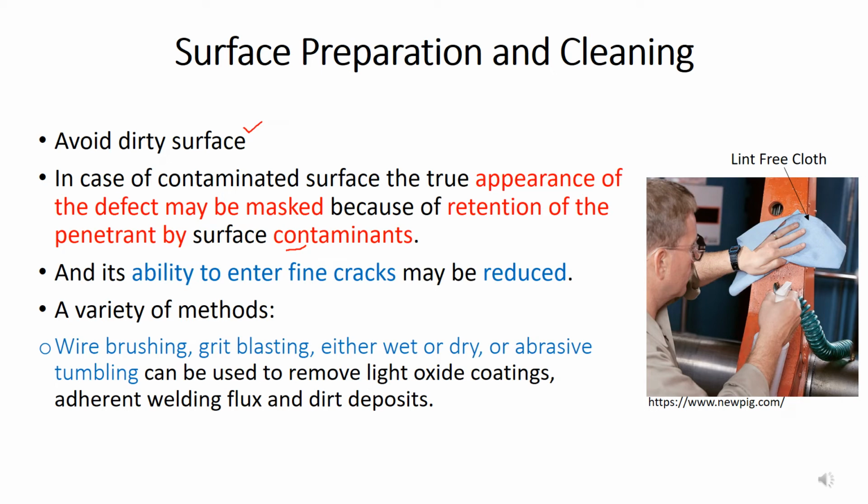Its ability to enter the fine cracks will be reduced because it is already having contaminant with it. And you can see we use a lint free cloth. A lint free cloth is a cloth which does not give any fluff while we are using it. The microfiber cloth which we get with spectacles is a lint free cloth. We use these lint free cloths for cleaning purposes.